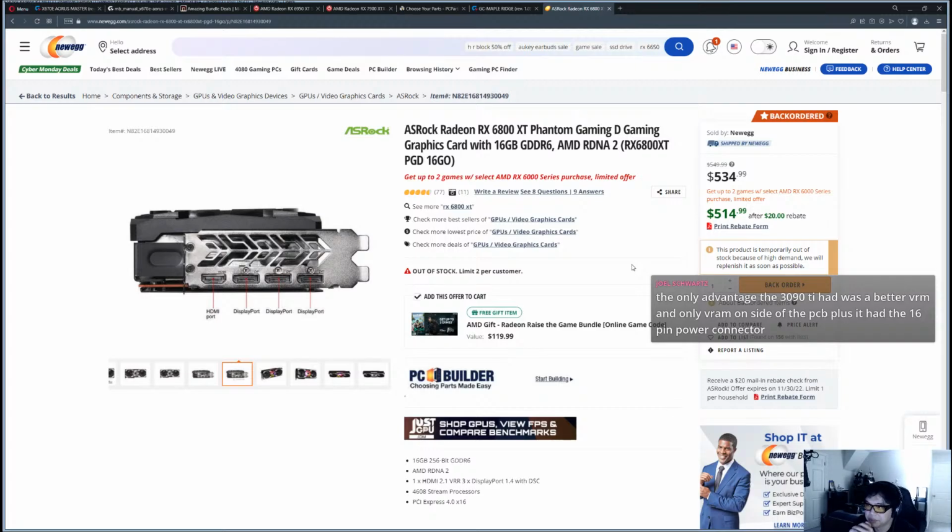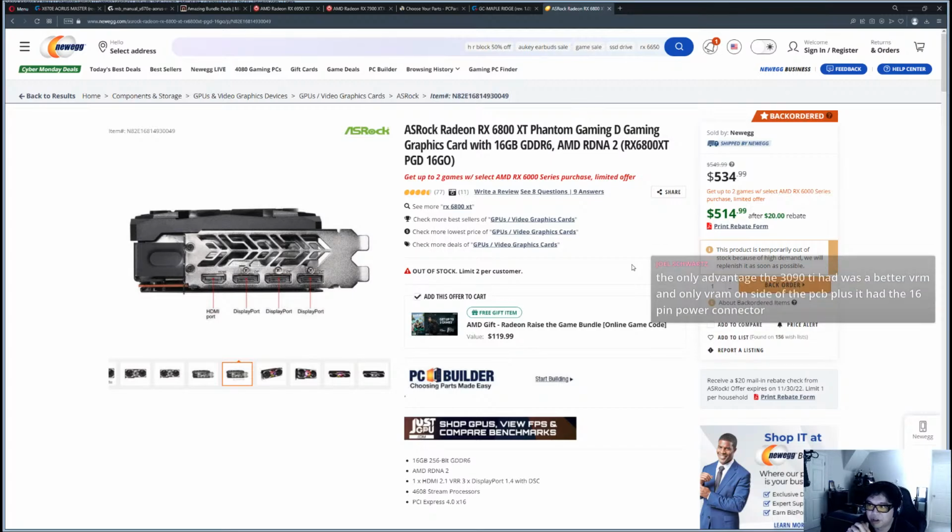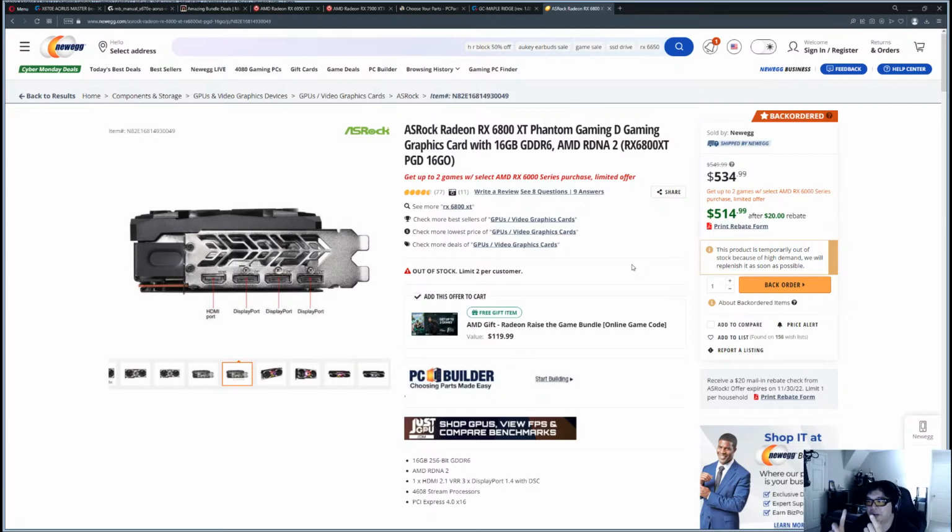Yes. Yeah, the 3090 Ti. So the 3090 Ti is going to be more reliable than the 3090. The 3090 is going to be one of those cards that NVIDIA is going to wish they never made the way they did, because I have a feeling that card in particular is going to have a lot more RMAs than the other 30 series cards. That's because the memory on the back usually cooks itself to death over a long period of time. And remember, they had a bunch of issues with 3090s dying when New World launched.